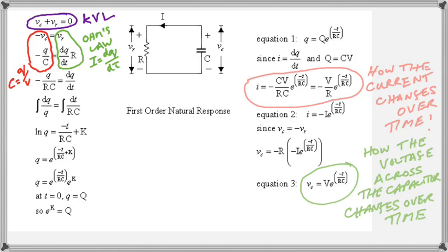So we come down here now and we look at this next one in green, and we've done the same thing with the voltage. The big V was the initial voltage and the little v is the changing voltage. So the big V is always going to hold on to its big value which it started as, but the little v is going to start with the big V because it's going to start basically at 1, and that e to the minus t over RC term is going to start basically at 1 and gradually decay exponentially to 0. So that's how that is accounted for.